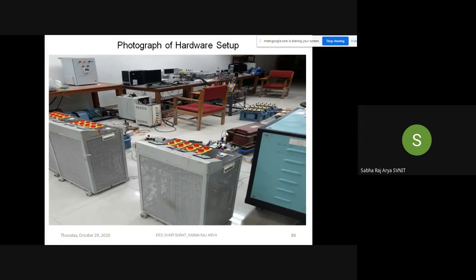Next, the main thing in this whole setup is how we can design the sensing elements and how we can connect those elements to the processor. You can design the sensing elements, voltage sensor and current sensor, and connect them to your ADC. So you can use a BNC cable. In a BNC cable there is one main and one ground. By that you can connect to your processor. The processor output goes towards your control desktop computer.